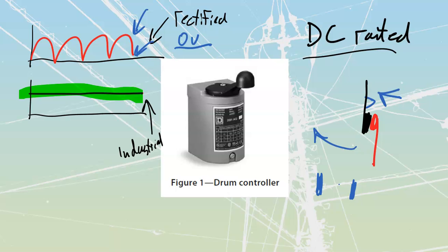For small DC motors, often what I'm going to do is stick in a SPDT switch. You should know these short forms over here. This SPDT would be single pole, I said the wrong one over here. DPDT, double pole, double throw switch that I'm going to switch out both lines with.